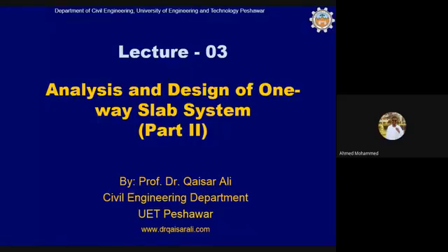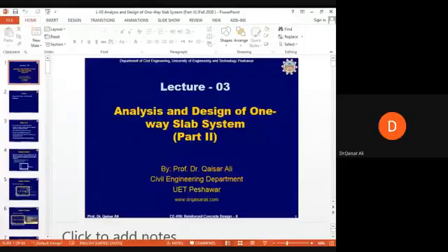Sir, I have seen a video for a simply supported beam. If you take a section from the middle, the main bars will be, for example, 4 bars and the hanger bars will be 2. But if you take a cut at the support, the hangers will be 4 and main bars 2. In the video, he said he is using it to support the shear at the support, not in the middle. So how can you explain that?